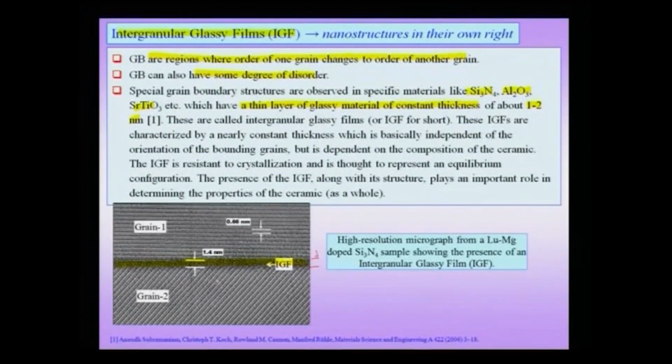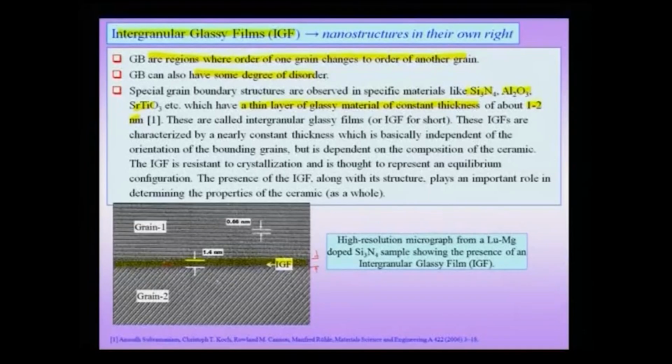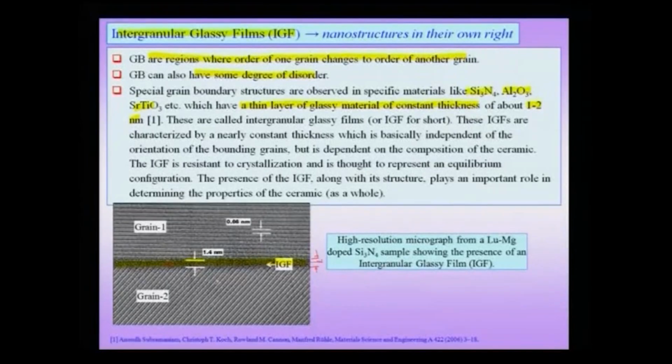This is the thickness, and this is the nanoscale structure. So, this amorphous-like region or glassy material is called glassy and we do not call it a glass, because the structure of this intergranular glassy film is different from the bulk glass which can be formed from a similar kind of material found, for instance, in a triple pocket down the grain boundary.